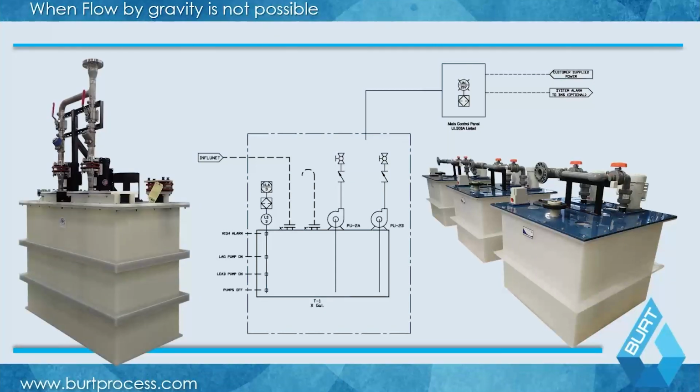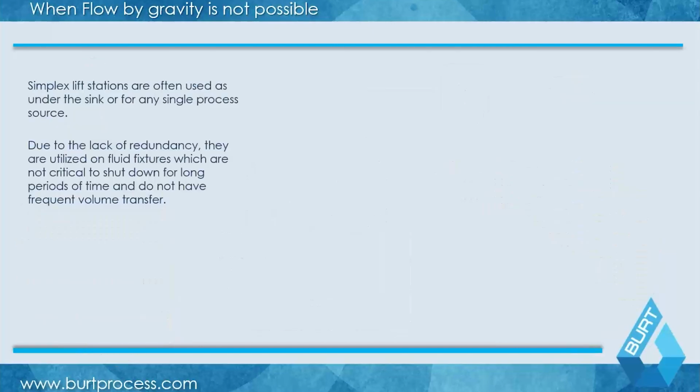Looking at it from a P&ID standpoint here, you have very small lift stations, and then quite a bit bigger stainless steel lift stations here. These really depend on a number of different factors. Lift stations are made out of very similar materials to what you're going to make the pH system out of: thermoplastics, potentially stainless steel. The relative process complexity is not as complicated as a pH system, since this is really just designed to transfer waste. But there are a lot of nuances to how these types of systems are built.